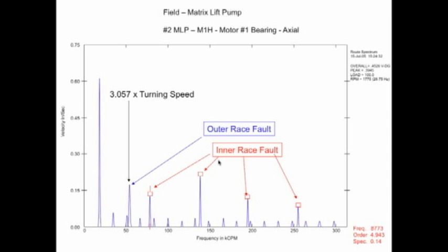So from a defect progression standpoint, this low frequency event, this imbalance we'll call it, or angular misalignment, puts some increased radial and axial forces on the bearing, which causes the inner and outer race defects to appear. Now, what happens over time is these non-synchronous peaks, these peaks that the arrows are pointing at, are going to get a little bigger, and then they'll start to get smaller and smaller. And as they get smaller, these other peaks that represent harmonics of turning speed will start to come up. So when the non-synchronous peaks start to get smaller and those synchronous peaks start to get taller, what we know is going on inside the bearing is the spalling has propagated around the race. The bearing is starting to loosen up. So the bearing's ability to produce these non-synchronous peaks goes down, and its ability to produce these synchronous frequencies indicating looseness starts to go up. Right? So that's a typical progression, and those frequencies match with an SKF 6311 for those of you who are interested in such things.